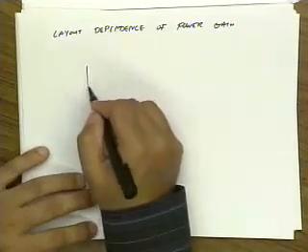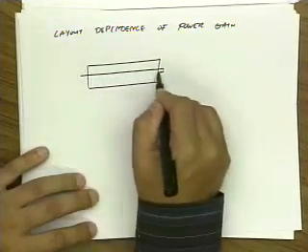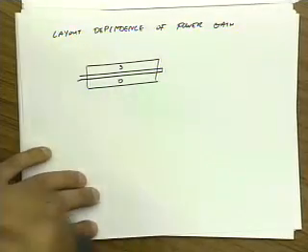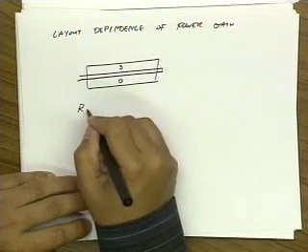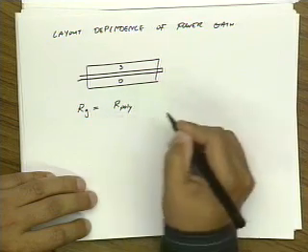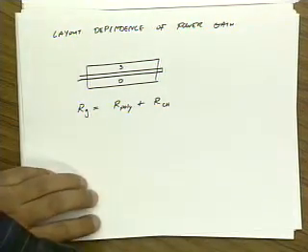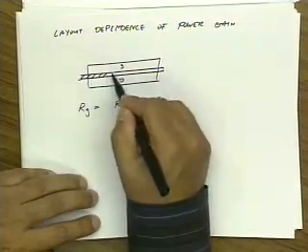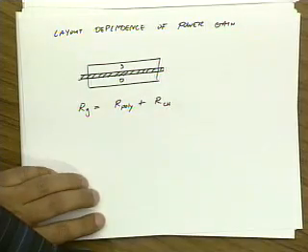So let's say you have a FET and you lay it out like this. This is the gate, this is the source, this is the drain. And remember, our gate has two contributions. Our gate has our poly plus our channel. Now the poly resistance is quite easy to understand. It's just the resistance, it's proportional to the resistance of this gate finger, right?